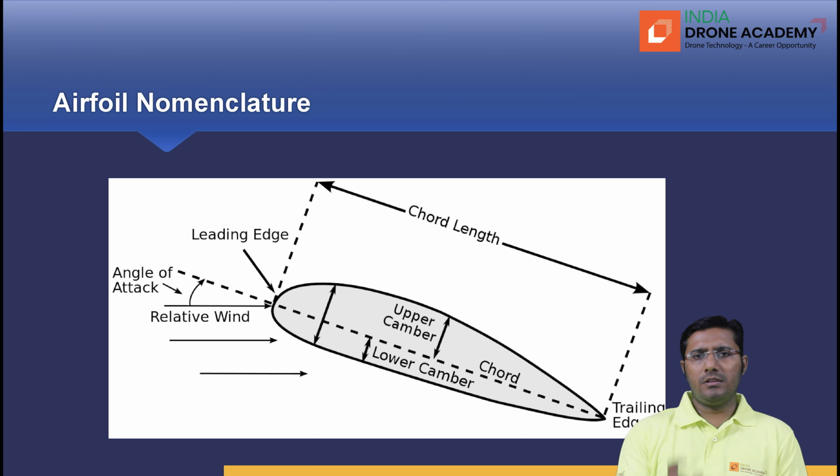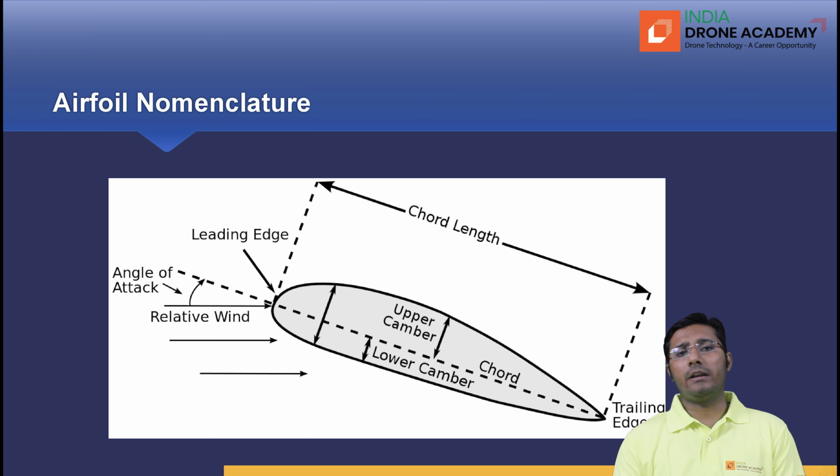And this can be seen here, the airfoil as the side view of the wing. So when the air approaches the wing, the airfoil, you can say this relative wind has some direction, has a velocity, meaning direction. So when one looks at this vector, one can easily see that this wind direction is making an angle with the chord line of the airfoil. So this angle is known as the angle of attack. Okay, alpha is a symbol which is generally used to represent angle of attack, and if this angle of attack is more, the lift will be more. If angle of attack is reduced, the lift will get reduced.